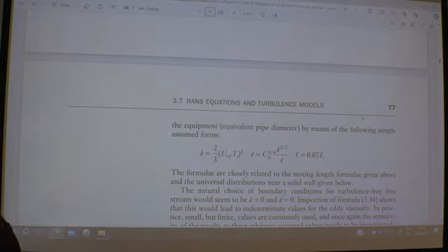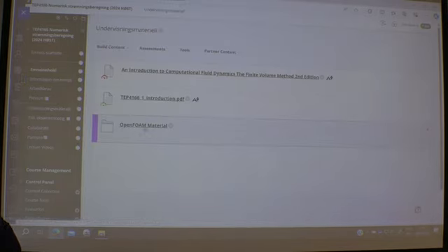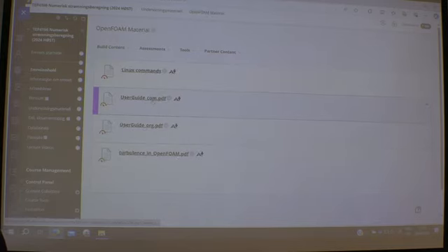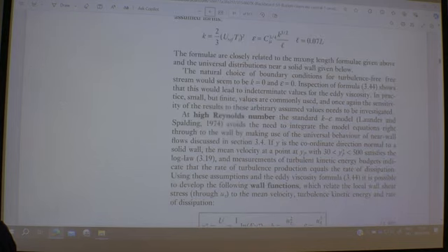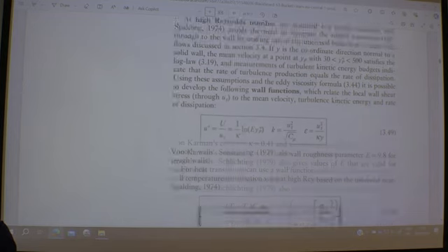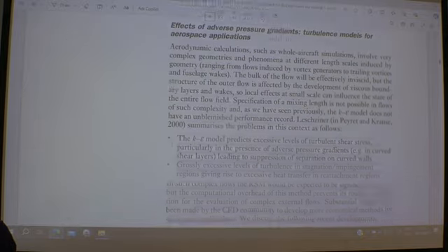You can also find them on the home page when you look at the OpenFOAM material. So inside the OpenFOAM user guide, you will also find these recipes, and also inside this one. I'll have a look at that one later. Turbulence in OpenFOAM. But here at least one recipe for K and epsilon. I think you also have another one for K and omega later on here.